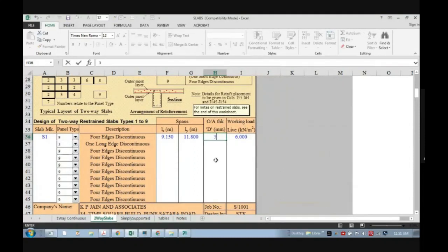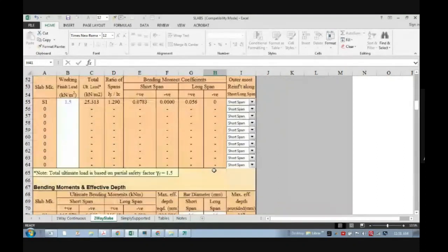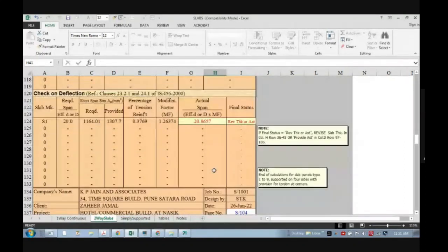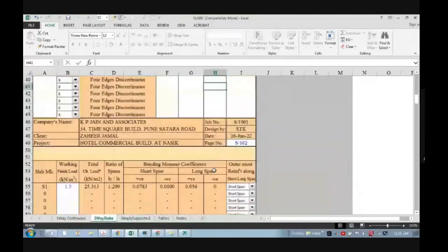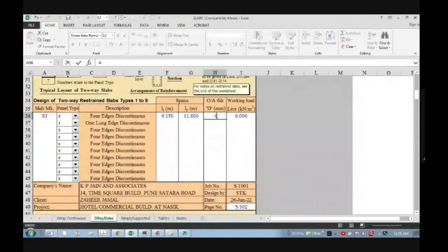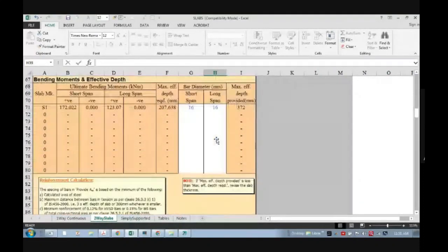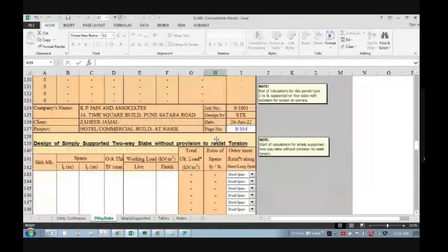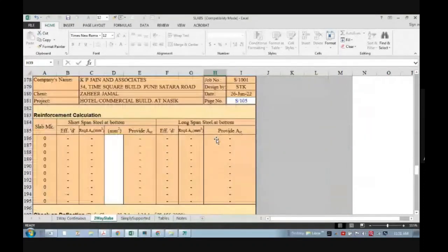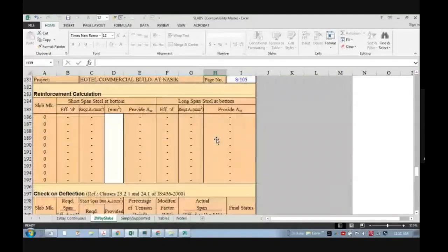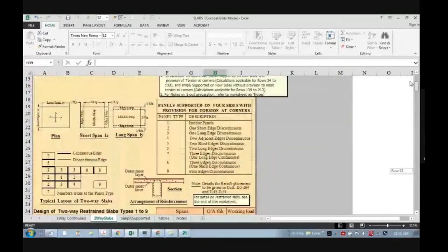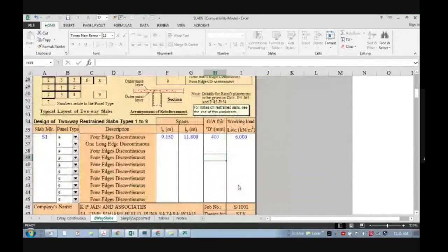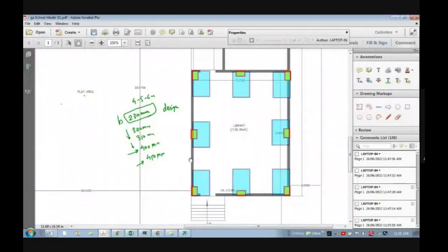तो मुझे लग रहा है ये 375 में बैठे. 400 thickness of slab is not a joke. Okay, it will definitely अभी पास हो रही है, but serviceability issue may be there. इतने thickness के लिए इतना बड़ा span है. So okay, but let's see, not bad. कर सकते हैं यहाँ.